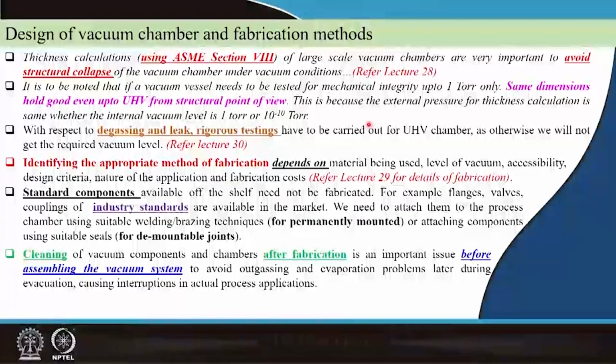Okay. Then from the ultra high vacuum point of view, leaks, degassing issues, you should know the physics of degassing, the chemistry of the degassing, what it is degassing. If it is degassing helium, how does it matter? If it is degassing argon, you do not care, let it degas, it is not going to interfere, it is not going to make compounds, because helium, argon, they are inert gas fellows, they are so inert, they will only be watching your stainless steel chamber or any other manipulators.